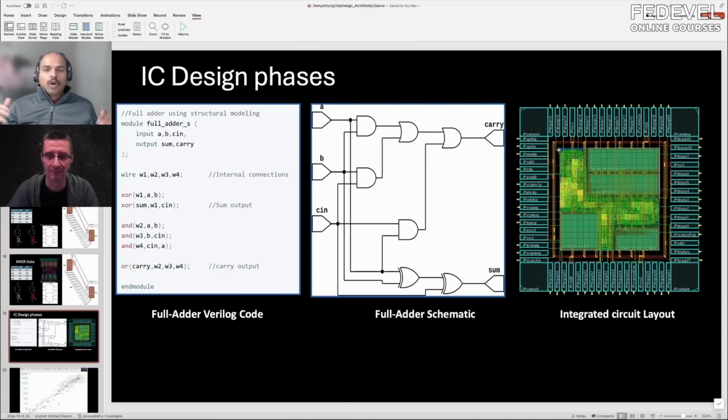We often end up with the tool coming back with two options. One is the tool can give up and say, there are 100 nets that need to be routed, I could only route 70 and could not route 30. That may not be helpful, so what we do is say, let's try to route all of them and tell me the areas where it is crowded.